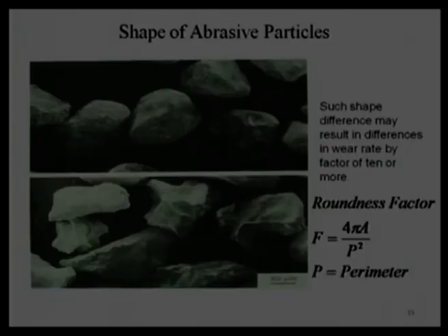If we are using particles as material to lubricate the surface, I can take a very simple example to demonstrate practical particle size. We say MR fluid, magnetorheological fluid, where particles are used, or iron particles are used, maybe having good hardness. Generally, we try to keep this particle as a sphere.